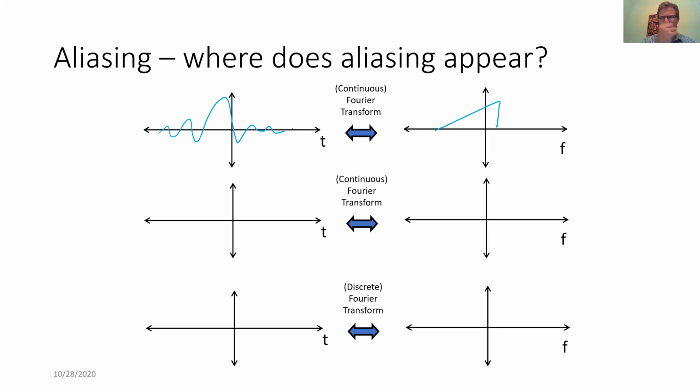And some guess at what the signal is here. Now, if we take this sample at some interval, recall this is our delta TS, we're going to get this repetition of the object at 1 over the delta TS intervals.